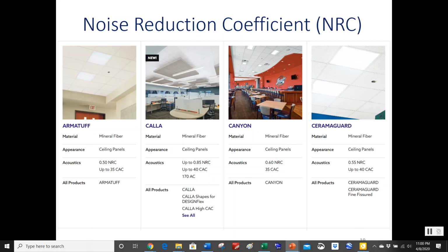If you have a classroom and you're putting in fan coil units, some mechanical systems have one big air handling unit on the roof that just pushes air out to all the other places. Alternatively, you might divide up all the spaces into different zones and have a small fan coil unit serving each space or each zone of spaces. Often you'd want to put that out in a corridor or over a storage room or something like that. But sometimes it might be above a classroom.